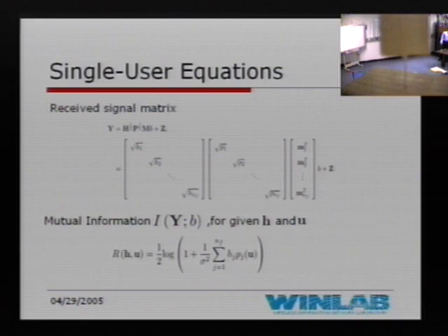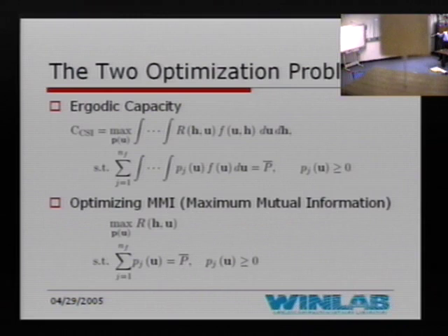Right. But the message is that for the single user they shouldn't really matter, and that's what we get, because spreading should not really give us anything. And they are also orthogonal even after you apply the channel matrix, because if you remember, my channel is fixed for all the chips. The gain is the same along these, and therefore they retain their orthogonality. In the most general case, it wouldn't be, but from the simulation we saw, that was the model they considered. So these are the two problems which I was talking about.